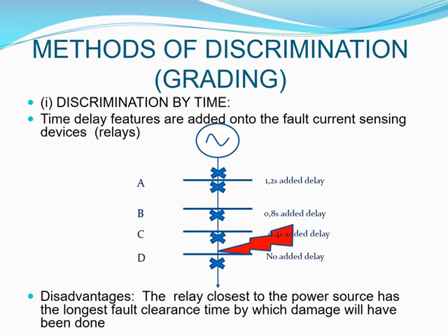If you're looking at the sketch that they basically have over here, you can see that at bus bar A, you've got two breakers that are looking in there. You've got a breaker on bus bar B that is below your bus bar. And then you've got one at C below and another one at D below. So what would happen is you've got this lightning strike that you see here, which is between your C and D bus bars. And from that point on, you can see that your first breaker, which was the one below D, has no added delay. You would expect it to immediately trip once it senses that there was that fault.